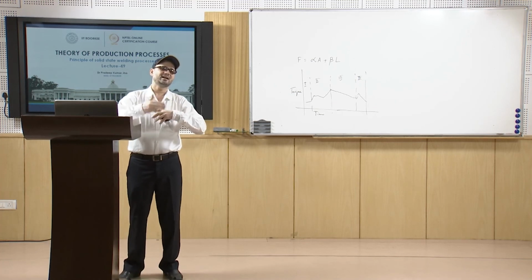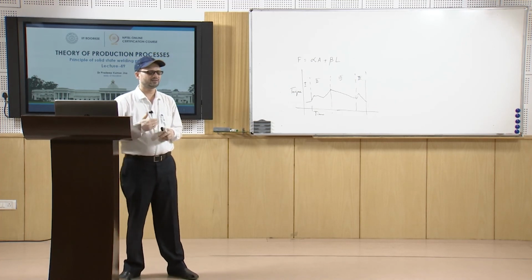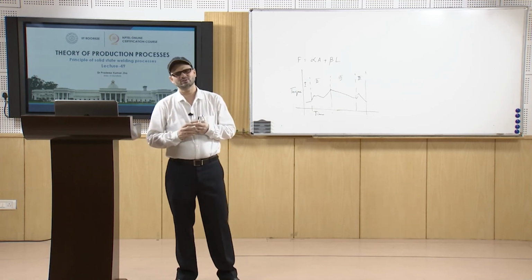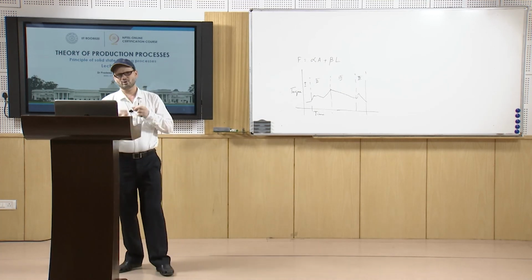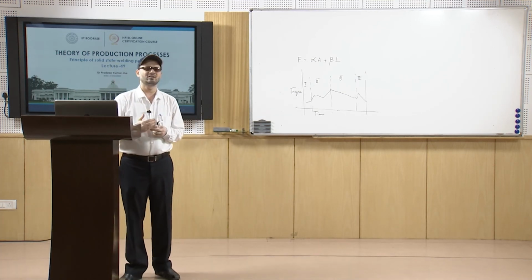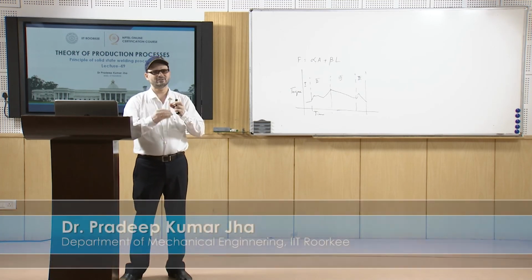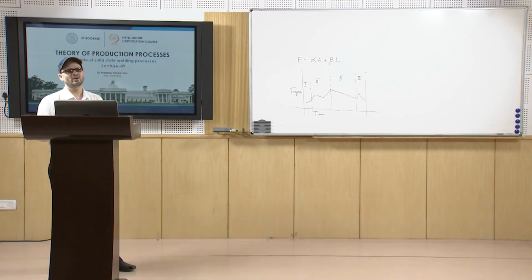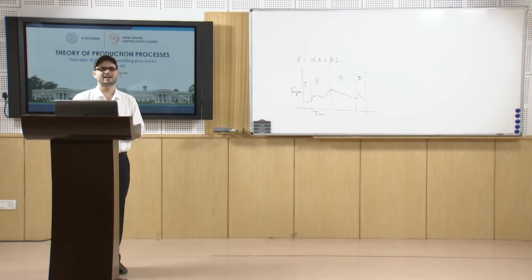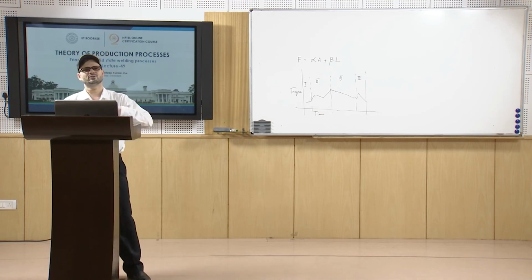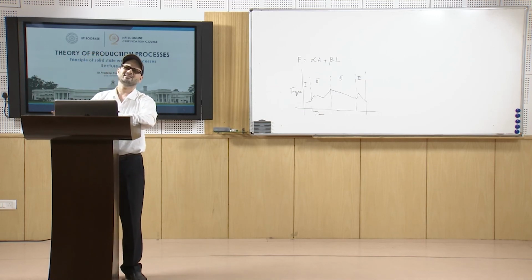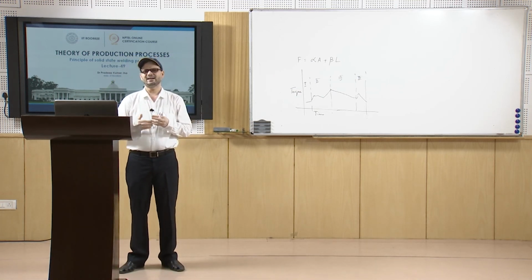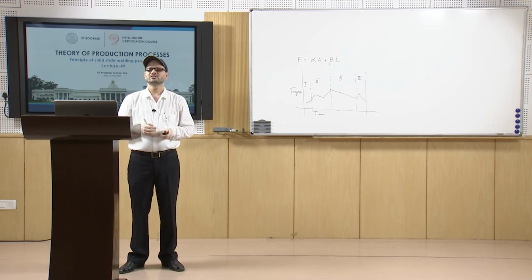Other than that there is also cold welding, cold forge welding, and hot forge welding. All these are based on the concept that you have the proper condition for the attainment of temperature, or in some cases diffusion bonding occurs, where because of diffusion at some temperature the bonding takes place. So these are the other processes based on solid state welding, which can be studied, and you can gain more understanding about such processes.